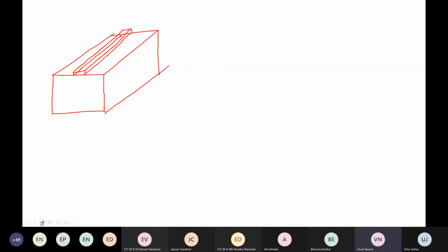Okay, great. Let me erase one line. Okay, so I am trying to draw a three-dimensional view of a MOSFET. Okay, so this is a p-type, this is n plus, this is n plus, and this is throughout your material. Okay, this rod, this is your polysilicon rod. Okay, here you have n diffusion, here you have n diffusion, and you have the wafer.